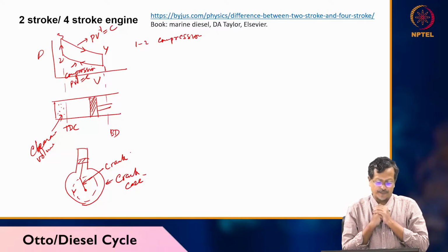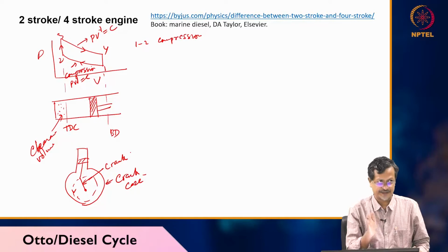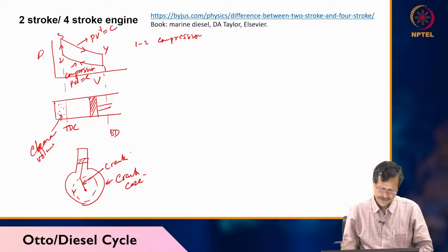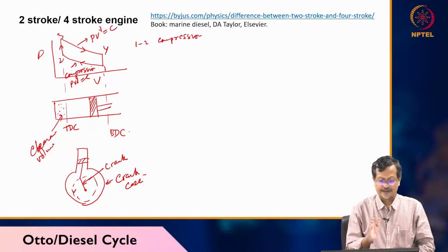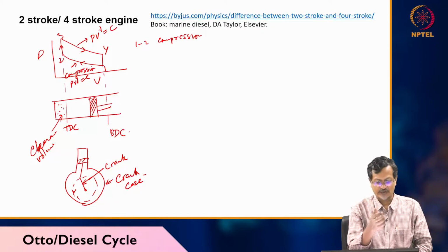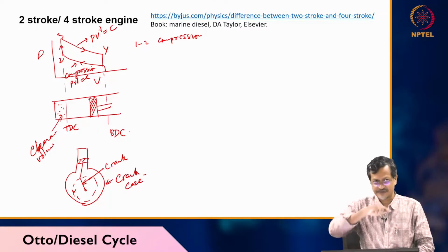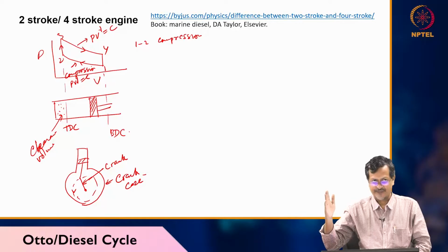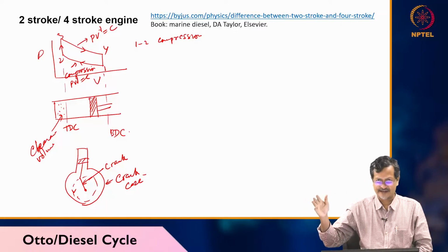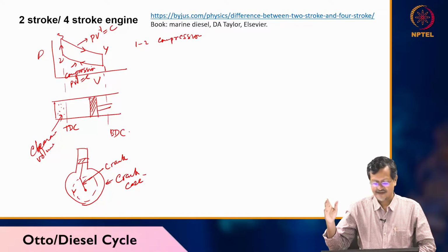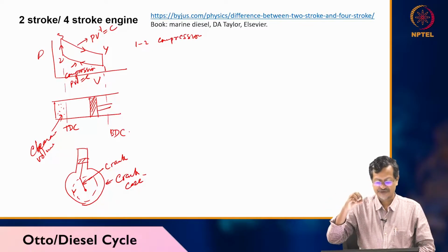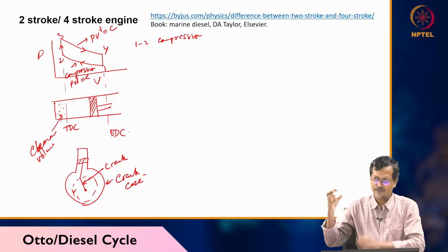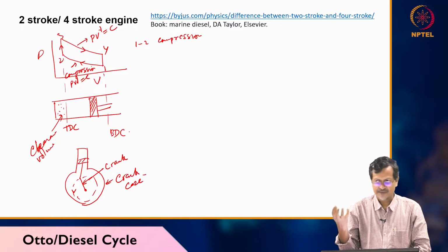Okay. Now, at 4, when the piston reaches BDC, bottom dead center, there instantaneously you have to remove all the burnt gas. But practically it is not possible because the crank is rotating continuously, the piston is moving to BDC, and instantaneously everything going out of the cylinder is not possible. So, you need a certain time for the burnt gases to go out from the cylinder. And again, you have to take the air and fuel mixture in at the same time. So, how is it possible? It is difficult, right.